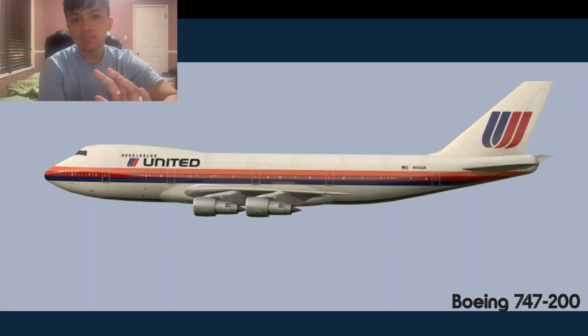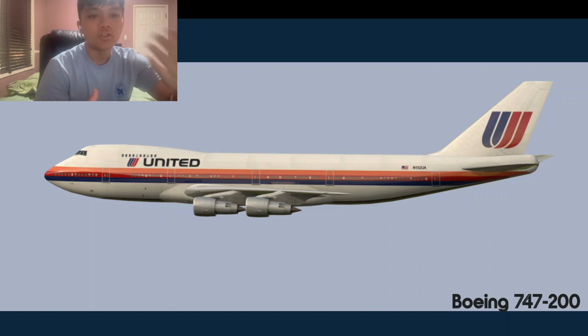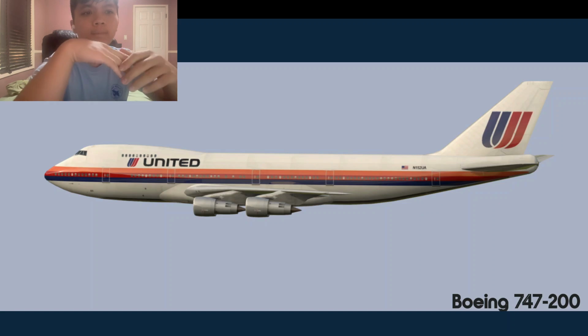For this simulation project, we made a couple of assumptions. That's what you have to do if you want to make a rigid 6-degree of freedom model for an aircraft. Some assumptions we did make were perfect sensors, so you're going to see that reflected in the model. Another thing we said was that all the forces and thrust produced by each engine are going to be only in the x direction.